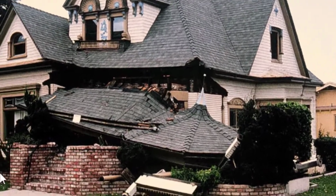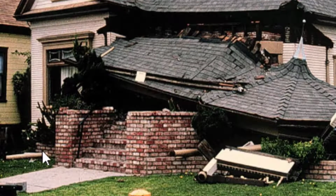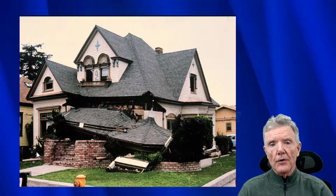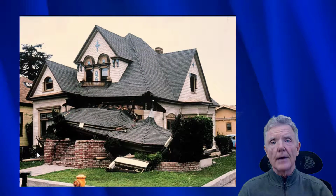Here's another good example of a cripple wall collapse. So this is the floor of the house now. And it used to be that you would go up the stairs and then into the house because it was elevated a few feet, and that was the cripple wall. And now the cripple wall has collapsed, and now the floor of the house is way down here on the ground. So the whole purpose of a cripple wall retrofit is to prevent that from happening.